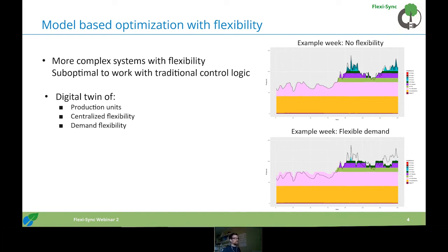And this is because of the big thermal inertia in the building. And this demand flexibility category also includes the buildings with both district heat and a heat pump, where you should really operate the control of these systems depending on what is on the margin at each point in time in the electricity grid and in the district heating grid to which the building is connected.